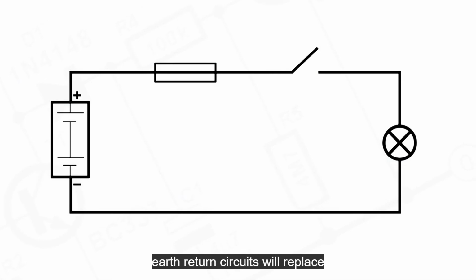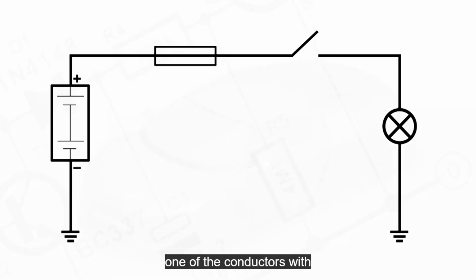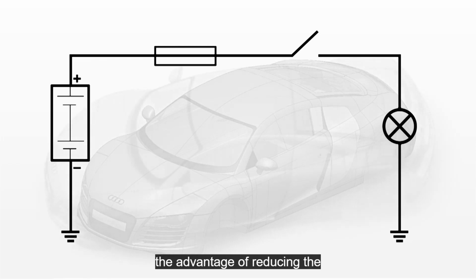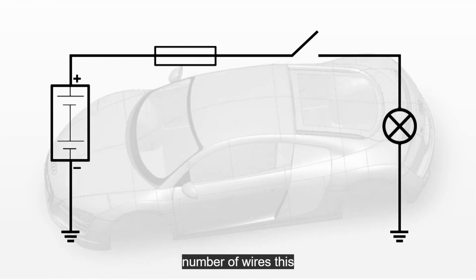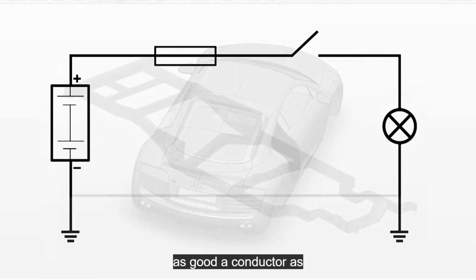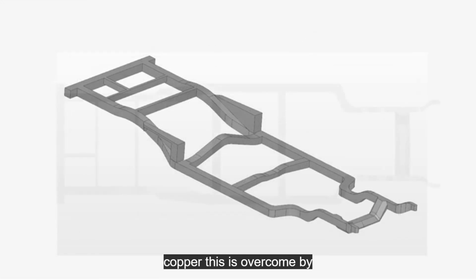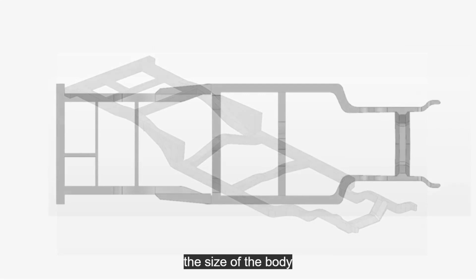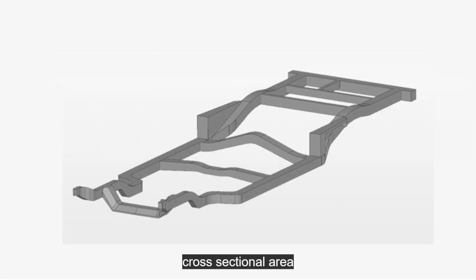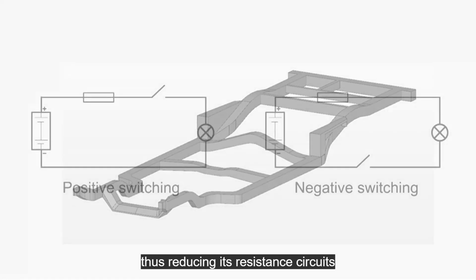Earth return circuits will replace one of the conductors with the body or chassis of the vehicle. This has the advantage of reducing the number of wires. This would appear to be a problem, as steel is not as good a conductor as copper. This is overcome by the size of the body and chassis. Effectively, it has a very large cross-sectional area, thus reducing its resistance.